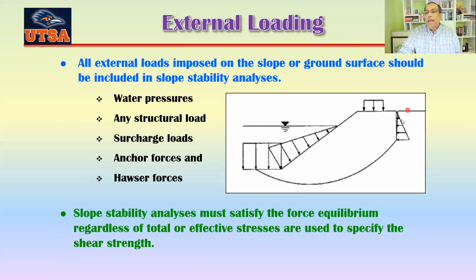And sometimes you can see there is a tension crack that develops in high plasticity soil when the climate or weather is very dry, all the water will go away. And if the water content is lower than the shrinkage limit, then you will see that the soil will try to shrink a little bit and a lot of tension cracks will develop, okay?